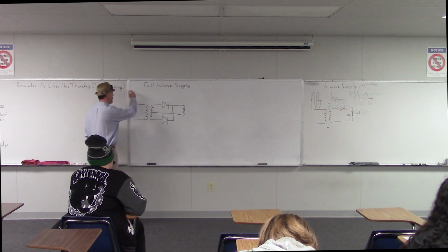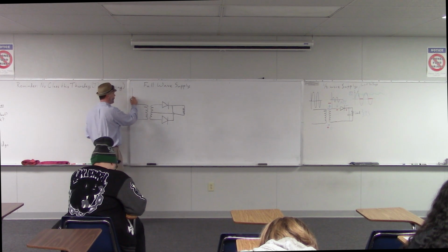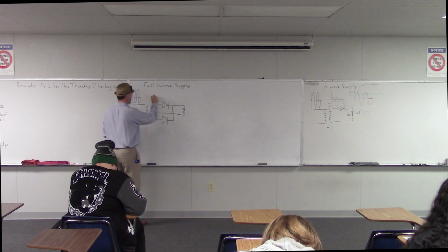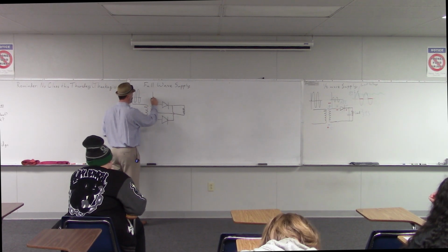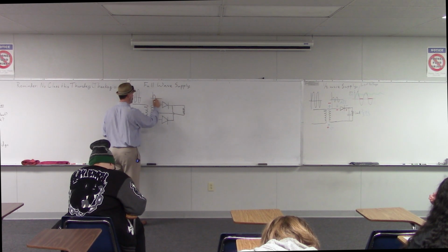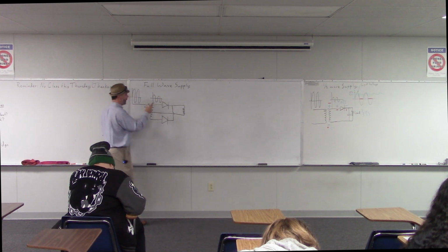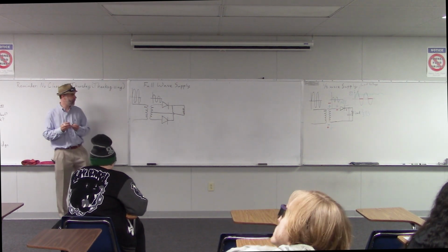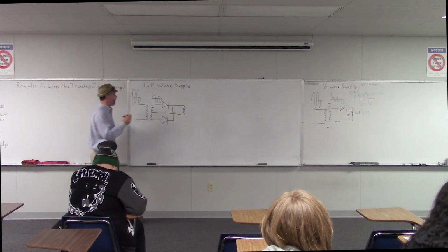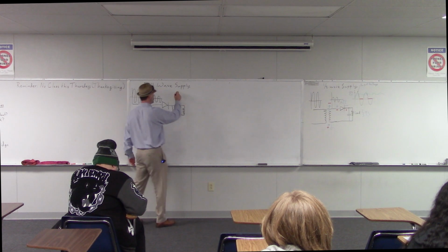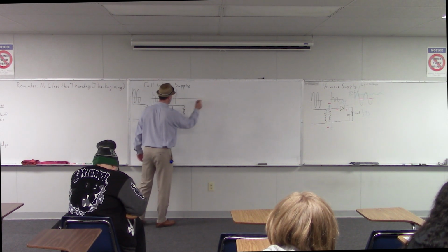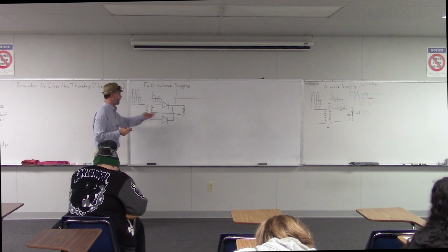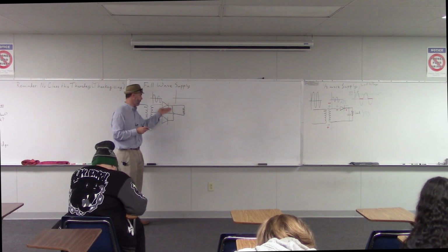So we can look at the signals again. Over here we have the high voltage AC signal, and then here we have a lower voltage signal, still AC. Do we still need a capacitor though? Yeah. So let me show you what the signal would look like before we put in the capacitor, and then we can compare it to afterwards. So then over here we have the rectifier. Again, we can examine the incoming signal and look at how that changes after it goes through the rectifier.